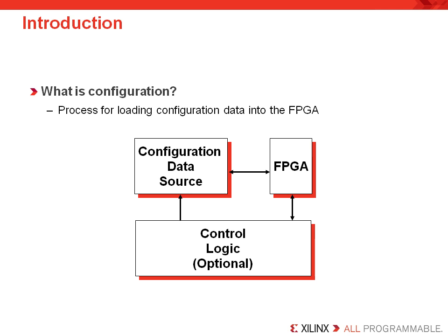In general, each of the configuration modes supports a variety of configuration methodologies. Keep in mind that FPGAs are designed to offer a wide range of configuration solutions in which some are simpler and need less debugging, and some are less expensive and give you a choice of memory components, and some offer a great deal of flexibility to suit a wide range of applications. In this example, the configuration data source could be at its simplest a flash memory component, or the bitstream could be stored on a network or downloaded from a laptop computer. The control logic shown in this diagram would have to be customized by the user.